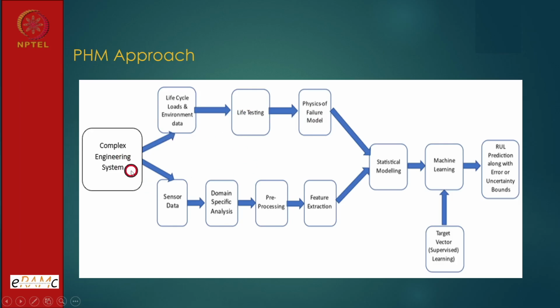And the other approach is called PHM, our subject. So here we are monitoring the sensor data, with domain specific analysis. If it is a bearing, a mechanical analysis will be required because there are four components: inner race, outer race, ball, and locking mechanism. So what is damaged? We want to get that information. So component specific expertise is required.